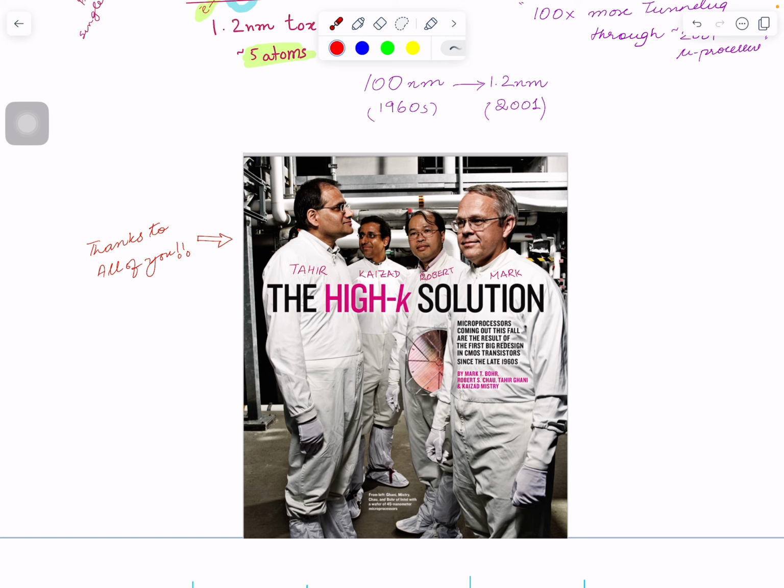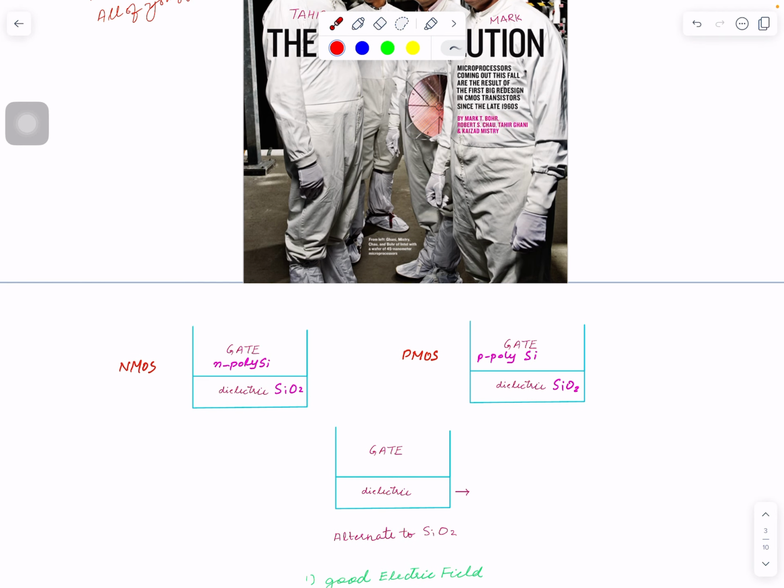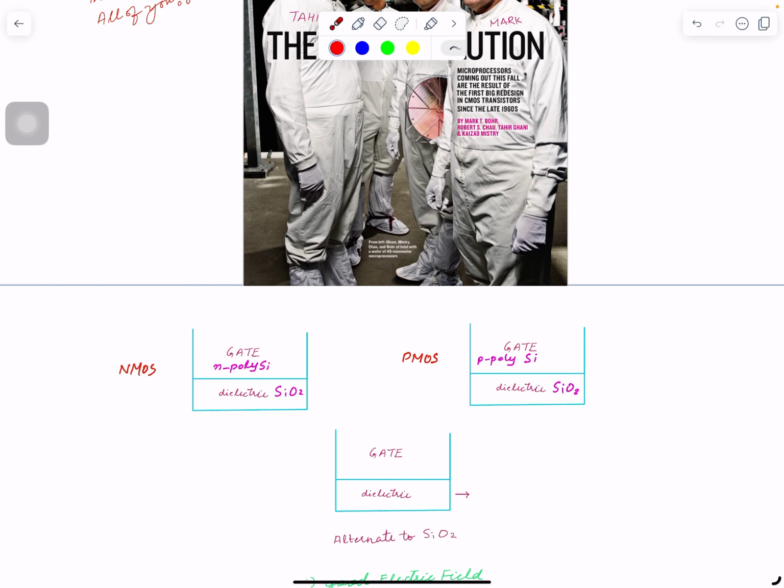In the next few minutes I will give you an overview of the 45 nanometer high-K metal gate story. That's really based on that paper. So you will have a lot more details if you read that paper. But I'll give you a higher level overview quickly in a few minutes, if you don't have time to read that paper. So look at the traditional case, the traditional case so far up to 65 nanometer. We have a gate that we call the poly gate, polysilicon.